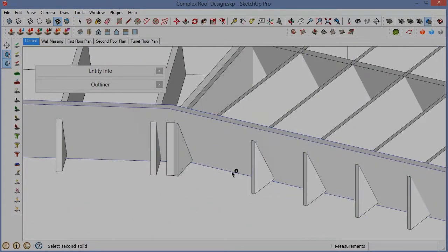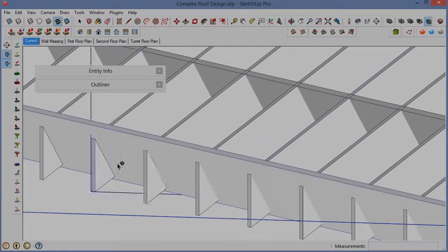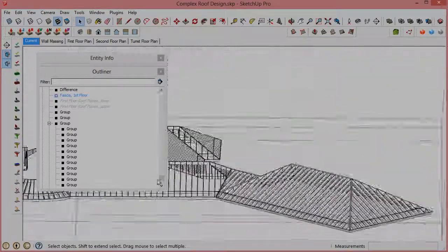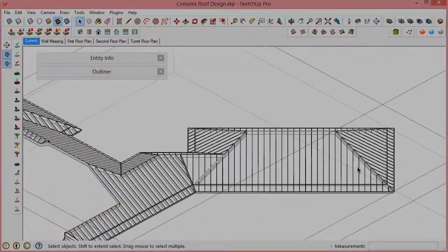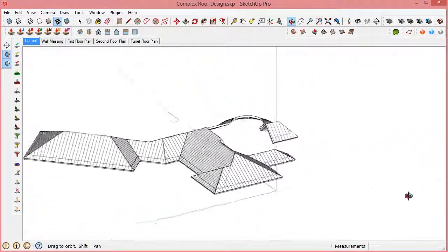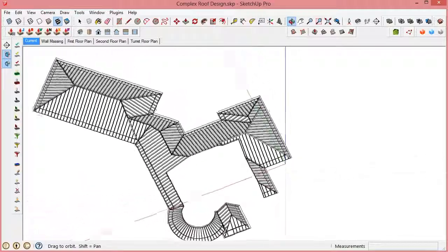After stepping through each rafter using the trim tool, and then coming back and deleting the tails, or using the circle tool trim method, and then editing the fascia a little bit, we have a completed fascia. I took the liberty of doing the entry fascia and frieze blocking offline. And there we have a completed first floor framing with frieze and fascia.